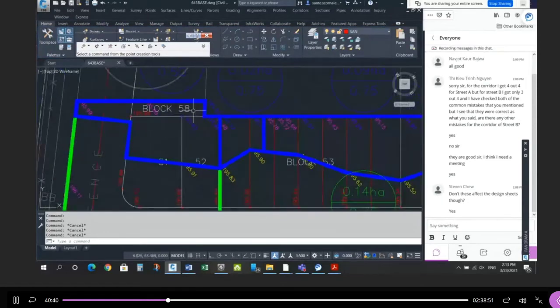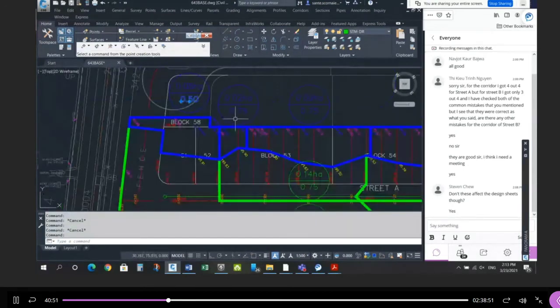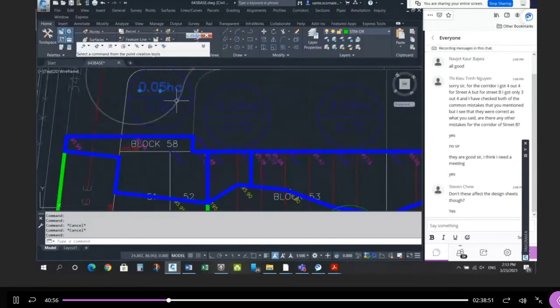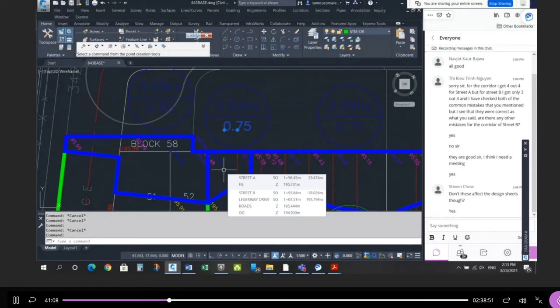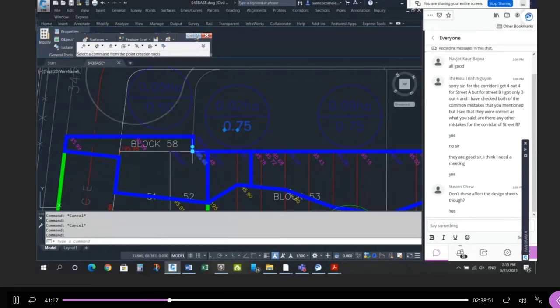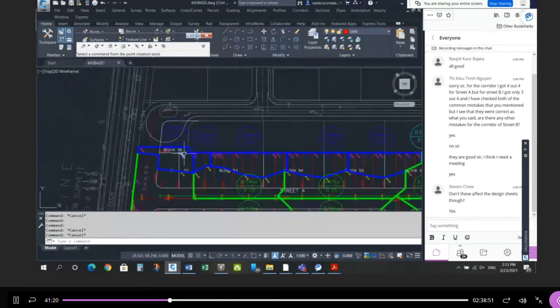All right, and then at this end, I know there's a catch basin here, but I have two different areas. This area is single detached homes, and this little piece is townhouses. So I have one at 0.5 and one at 0.75. Now, this 0.75 is so small that I could just make this 0.07 at half, or I can be conservative and say 0.07 at 0.75. I can treat this piece as a townhouse along with this piece and be conservative and send that area to the north. And if that works, then certainly I know this is actually smaller. It'll be fine, right? But technically, there should be two areas that drain to the catch basin that's right at this location here.